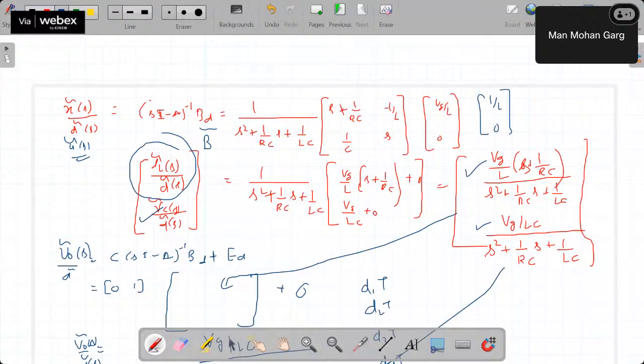True. Now, similarly, when you have more than one switch, two switches, like if you go for multi-port converters, then you have 3 modes, sometimes 4 modes, right? Then you keep one switching cycle constant. Within that cycle, only those modes are repeating. Even when we read about soft switching converters, they go for 4 modes. But whenever one particular mode is happening, we have a linear circuit in which either our voltage is there or your switch is there, and inductor and capacitance. Those equations we can easily write.